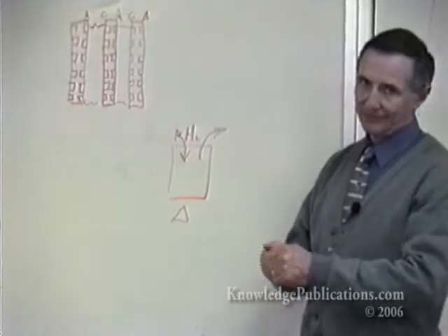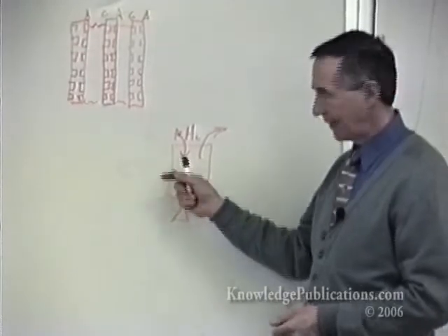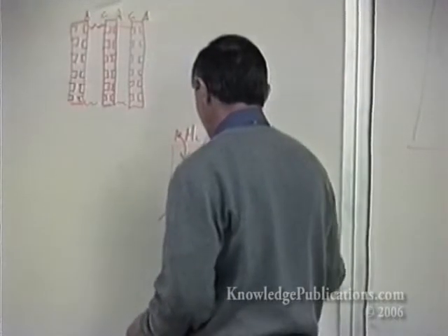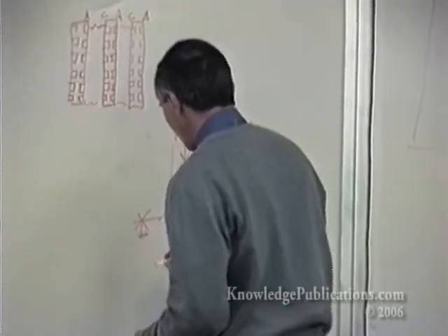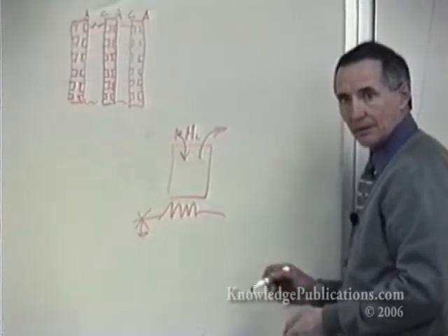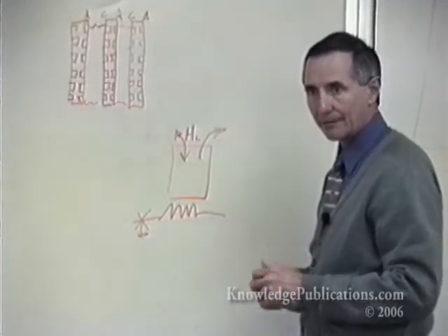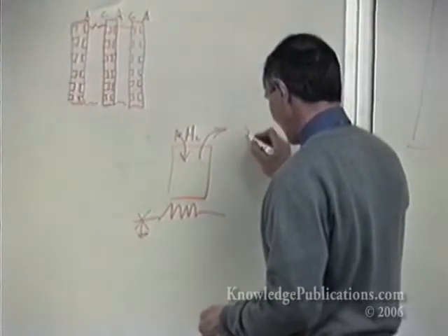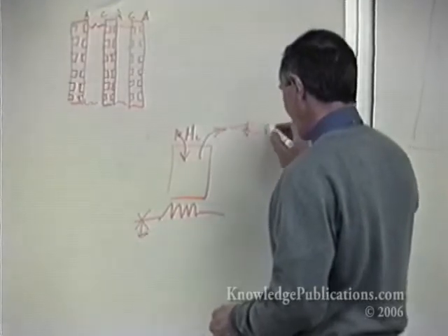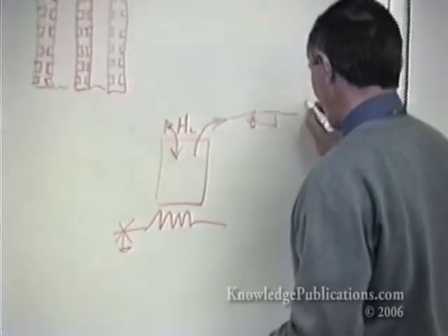You can produce 400 psi, one step, out of a hydride by cyclically adding the heat. So you turn on a valve to circulate the 80-degree water to this unit, and it drives off high-pressure hydrogen. You take that high-pressure hydrogen one of two routes. You take it through a small motor and get motive power out of it. You can run this through, for instance, a small turbine or a small piston expander and run it to low pressure and low temperature. The idea is that once this is expanded, it goes to a low temperature.